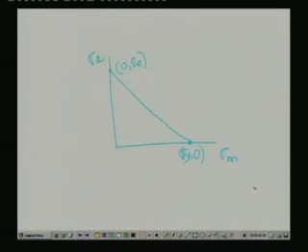So, if we consider the equation of this line, then you can see very easily that we get an expression, just an equation of a straight line: sigma A minus sigma E equals 0 minus sigma E divided by sigma yield point minus 0, times sigma mean minus 0.